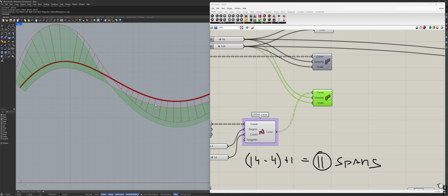Now, why was that? Well, that's because when we shrink something, when we make it smaller with a very specific constraint, which means normal direction, our parameterization of a curve changes. It was fluid and natural in one state. When you shrink it, it becomes almost impossible to maintain curvature and at the same time have the proper distance between them. So the tighter your bands, the more aggressive your form, the harder it will be to shrink it and keep your curvature. Because once again, all the parameterization changes, all the angles will change. And sometimes you can come to a situation where you have overlaps, because there's just not enough room.